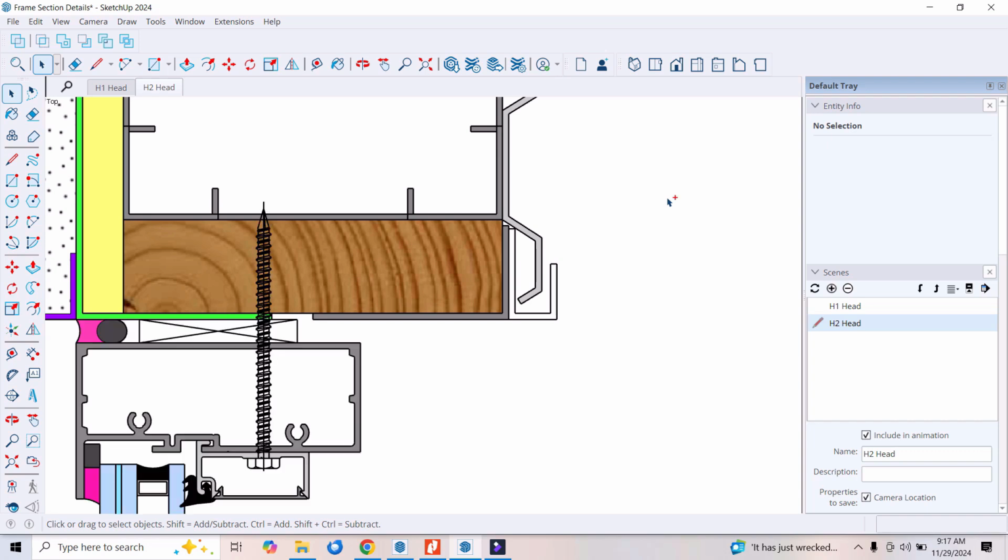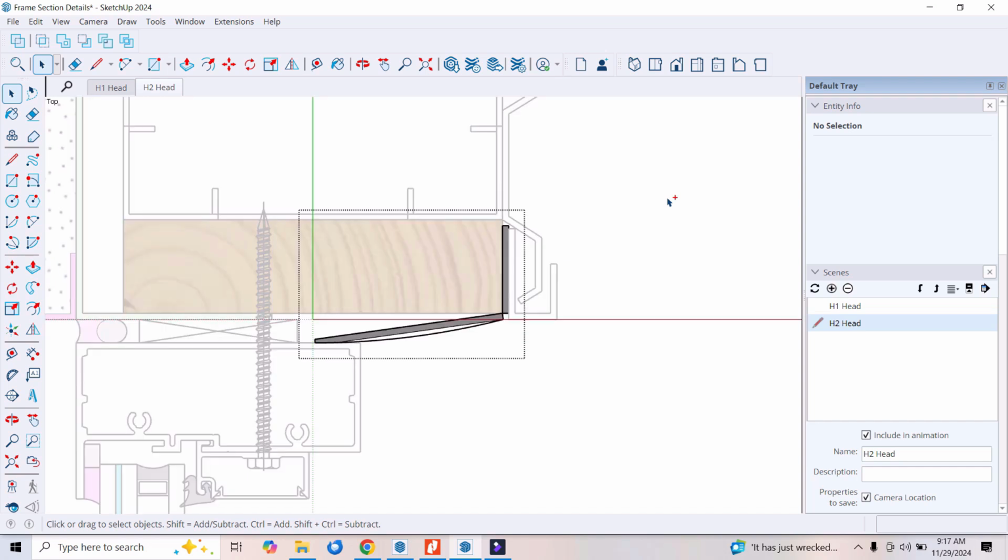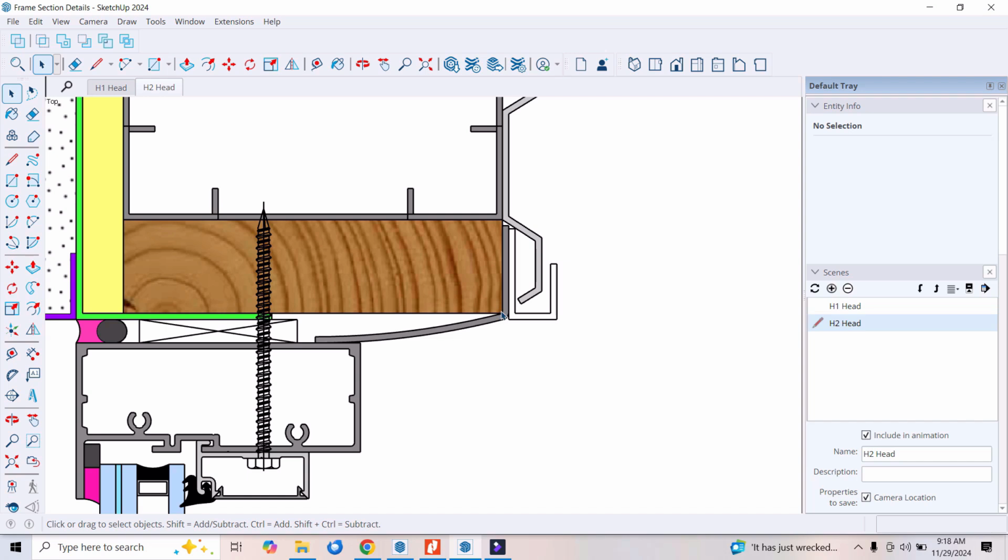I'm going to locate head detail just so I have the perspective, and then I'm going to modify this metal trim that they otherwise should expect to have. All they have to do is furnish something that has maybe a 110 degree angle, and then it will fill up this whole gap. Change the angle in the metal a little bit, and you eliminate a ton of work.